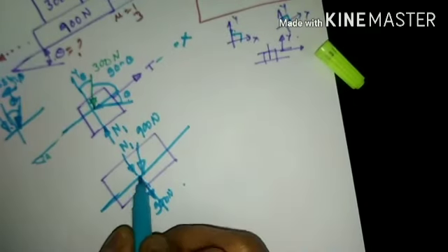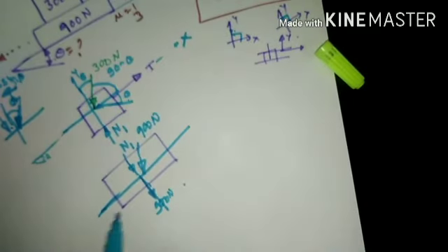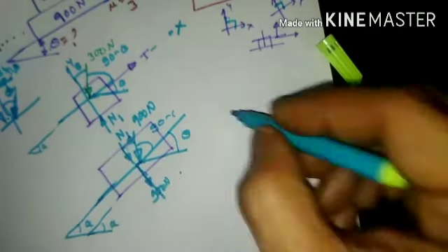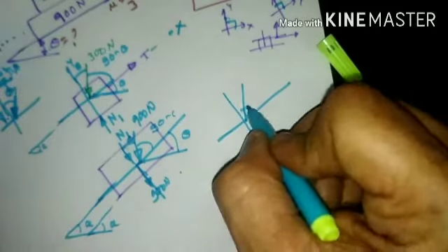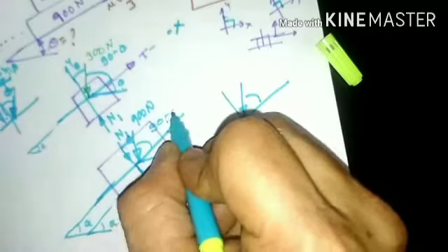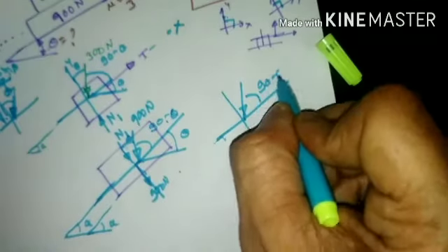Now here, when you transfer in the downward direction, again the inclination made here is theta. Likewise, the inclination made here shall also be theta. If you transfer the inclination here, this will be theta. Further back, this will be 90 minus theta, and this again shall come out to theta inclination. If I separate only the 900 Newton, which has been placed here, the inclination here shall be 90 minus theta, here it shall be 90 minus theta, and this inclination will be theta.